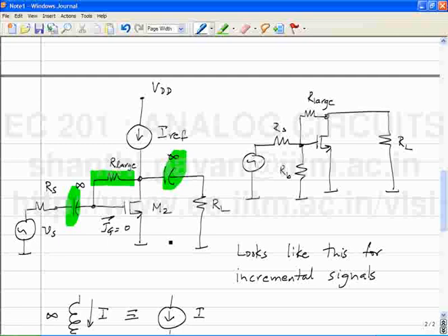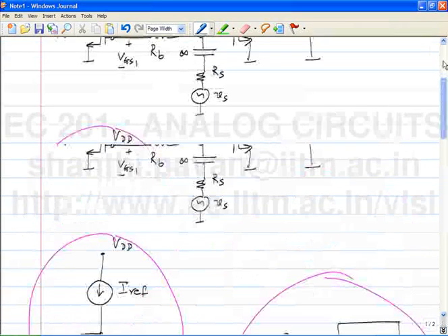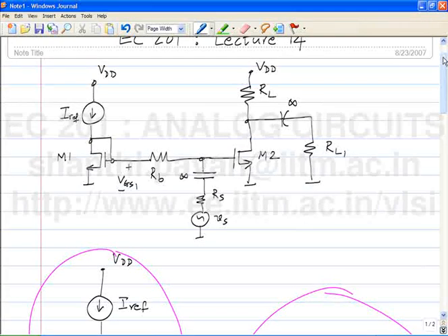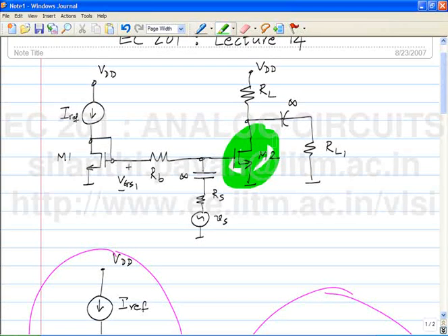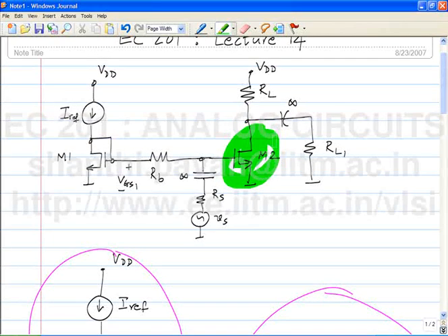Okay. So in the circuit with the current mirror, was there any freedom in choosing the drain quiescent voltage? How can I change the quiescent voltage in this circuit at the drain? What determines the quiescent voltage at RL? The drain of M2? ID, okay. It's VDD minus ID RL. ID is presumably fixed. So there are a couple of ways of varying the quiescent value. One is to vary the VDD, or if the VDD is fixed, one can vary RL and take the change in the gain that you get.